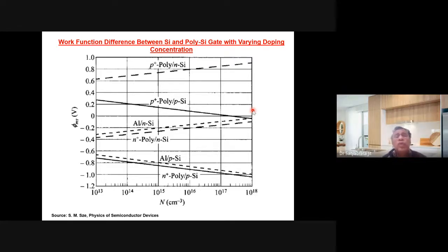What is the beauty of polysilicon? Now here a little bit I would like to mention, for any semiconductor, if the doping concentration is increased beyond a certain level, which we call the Mott transition level, then every semiconductor starts to behave just like a metal. And here this property is used. The polysilicon is heavily doped, and as the doping is increased, it behaves just like a metal. So the polysilicon, again, is compatible with the SiO2. Okay, so the device fabrication will be much easier.